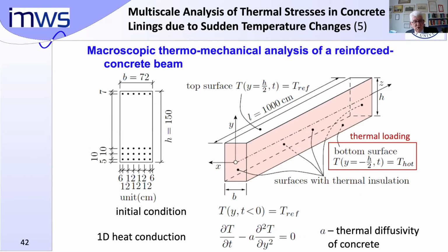Okay, Dr. Hui Wang analyzed a macroscopic reinforced concrete beam. The cross section is shown here with the reinforcement in the beam as such. We considered thermal insulation on the side faces in order to be able to apply a very simple differential equation, the one-dimensional heat conduction equation.